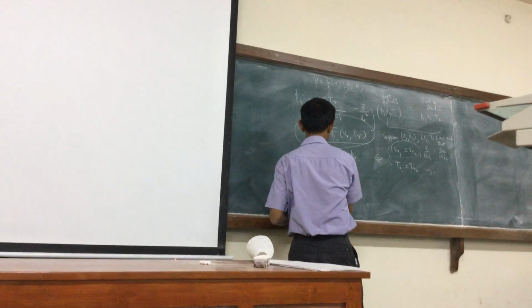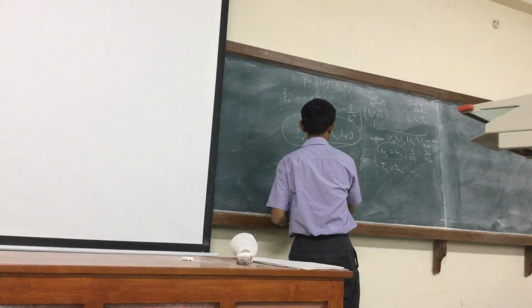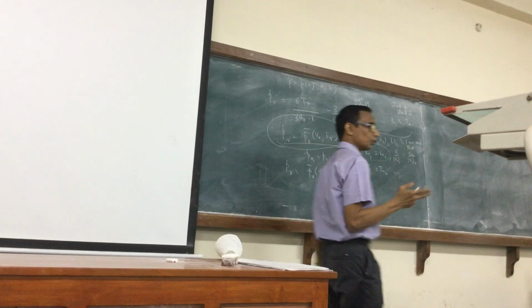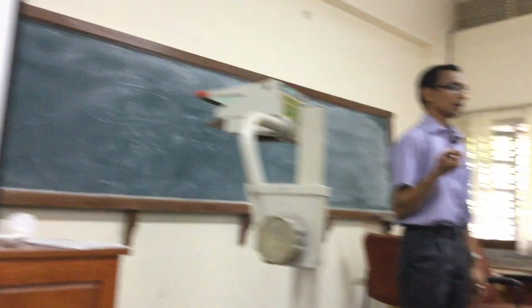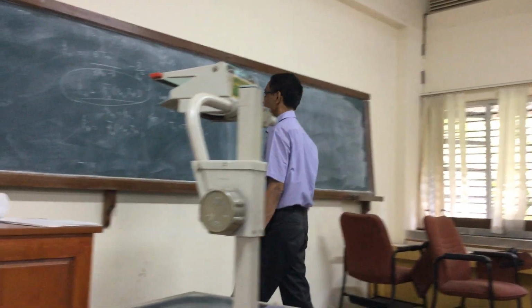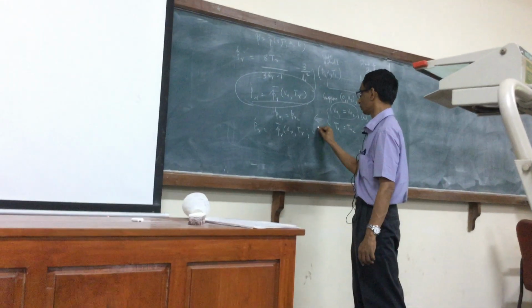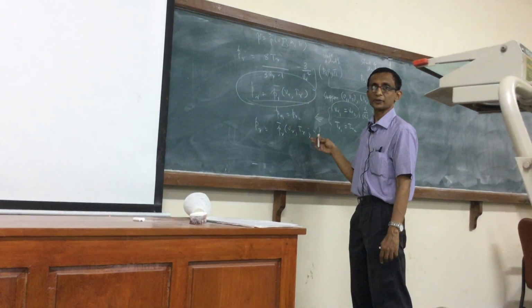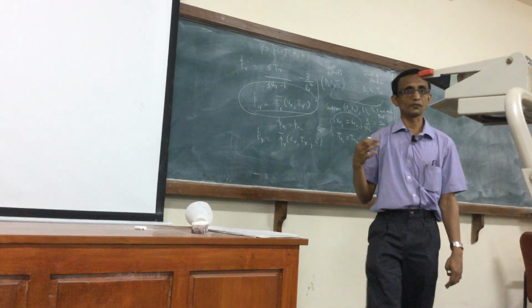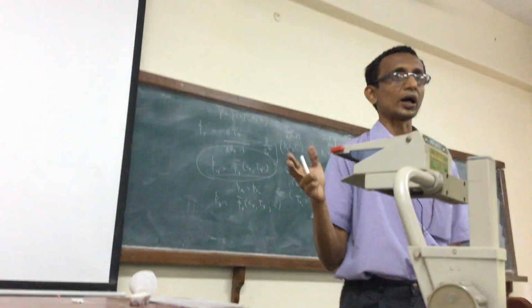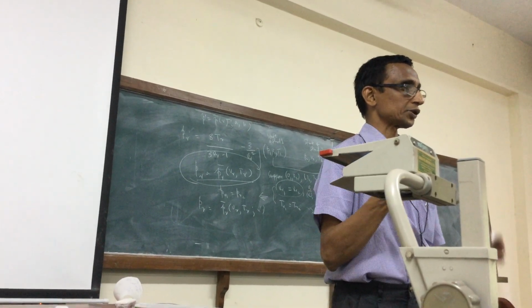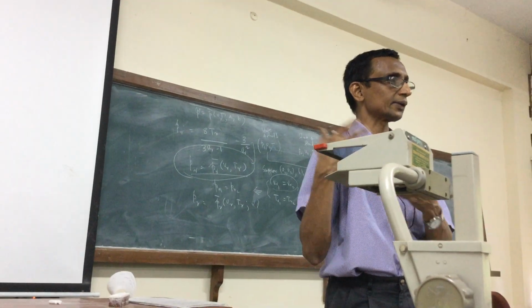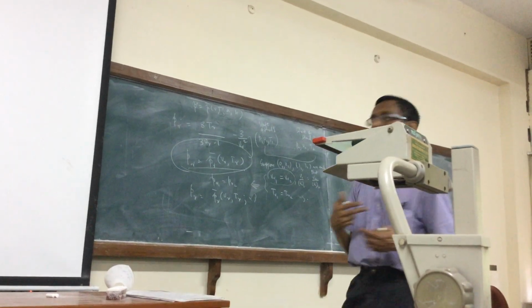So the question then is, suppose we introduce another parameter. Not all fluids will follow a universal correlation, but we introduce one additional parameter, and let's call it alpha, which will depend from substance to substance. Then all fluids with a particular value of alpha will have a universal correlation relating PR, VR and TR. This is the history of the corresponding states type of correlation.